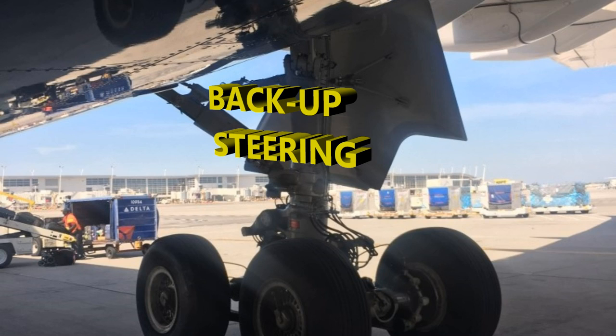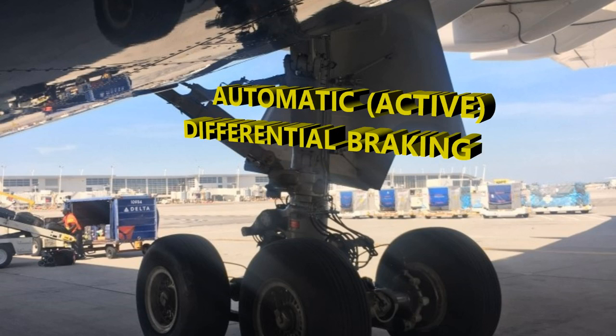Say there's a blockage of the active runway on landing, it's going to be possible. So you have a backup steering mode that's used for this. And this active automatic differential braking is just allowing the flight crew to leave the runway with the hand wheels.